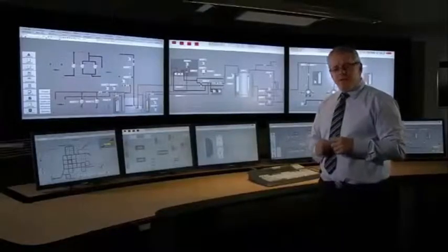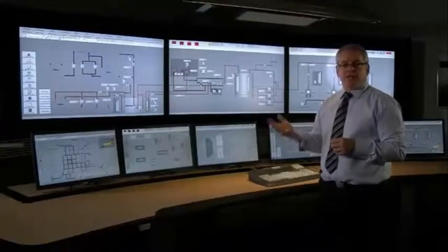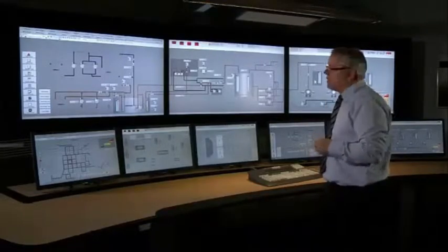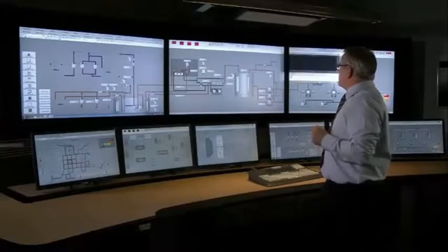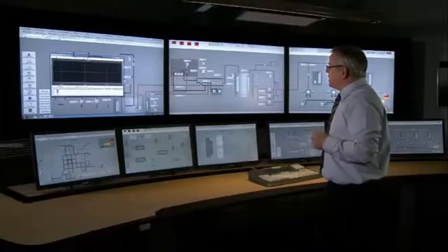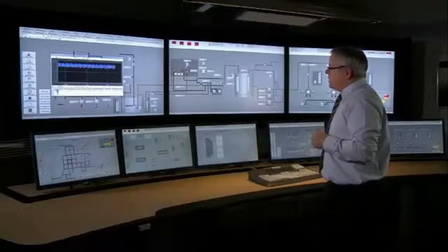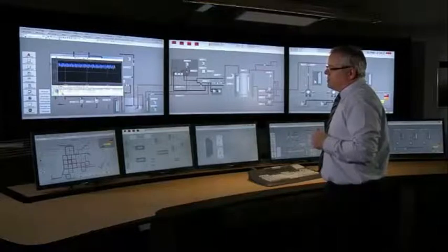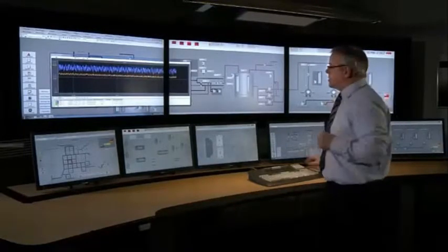800XA also provides easy access to typical user functions or maintenance functions such as operator trends, alarm lists, or documentation that may be required to do some troubleshooting. Some typical information is we're able to get access to an operator trend, and this operator trend displays no data at the moment, but we can simply drag and drop information directly from the workplace into the trend display, and this will then display any logged or long-term data that's available within 800XA. We can utilize the full workspace there.